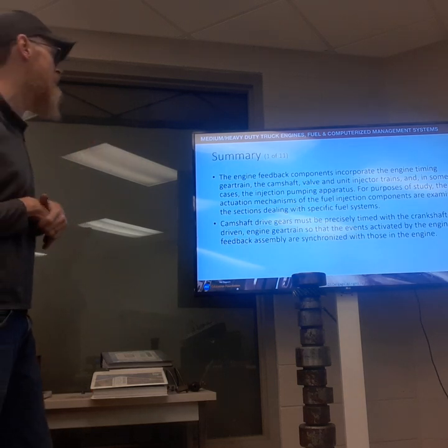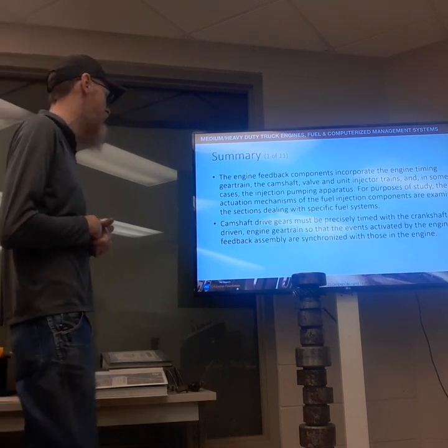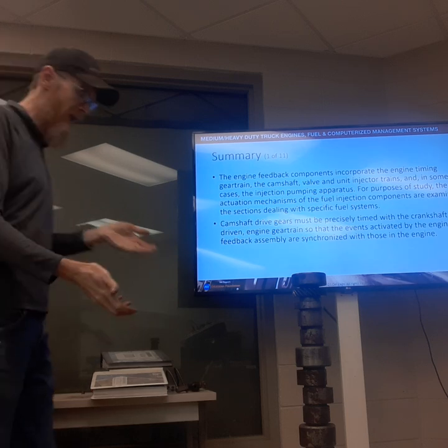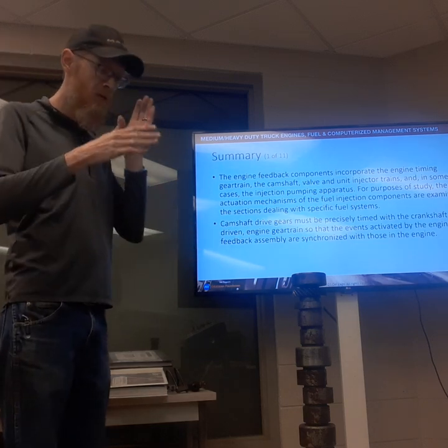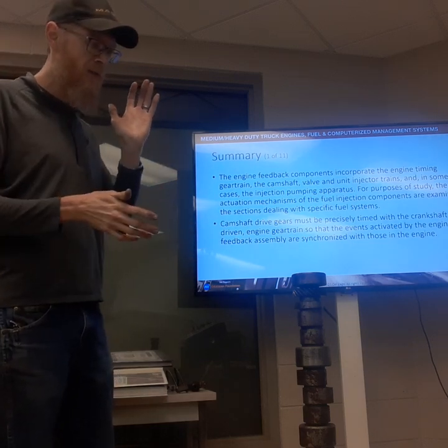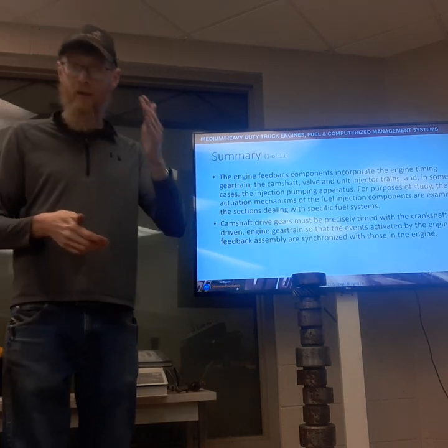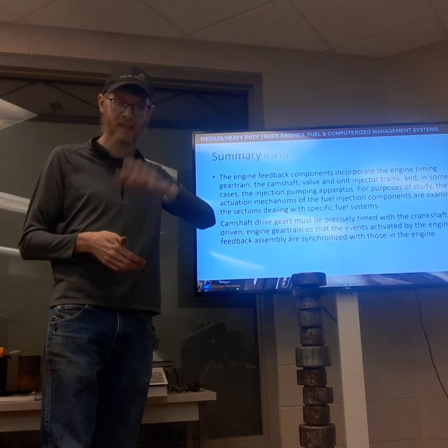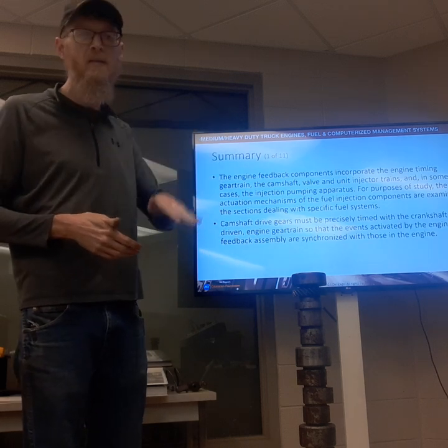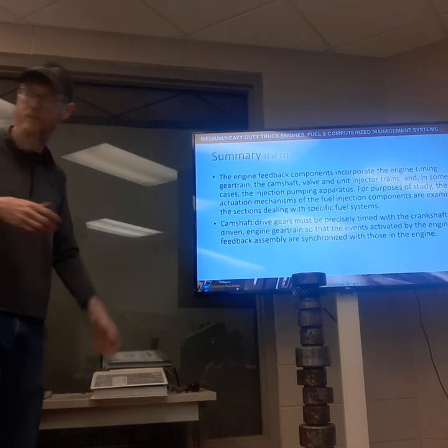Camshaft drive gears must be precisely timed to the crankshaft. Obviously, if we don't have the camshaft timed correctly with the crankshaft, our intake valves, our exhaust valves, our injectors are not going to do their job at the right time in relation to where the piston is in the cylinder.